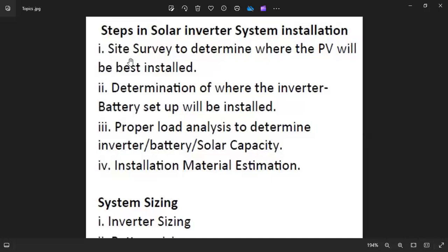Okay, that's fine. So the BMS must be working, you understand? And if the BMS is working well, I believe you're good to go to install it. Though the battery will definitely be installed with an inverter system, and as you all know, the inverter system needs ventilation.